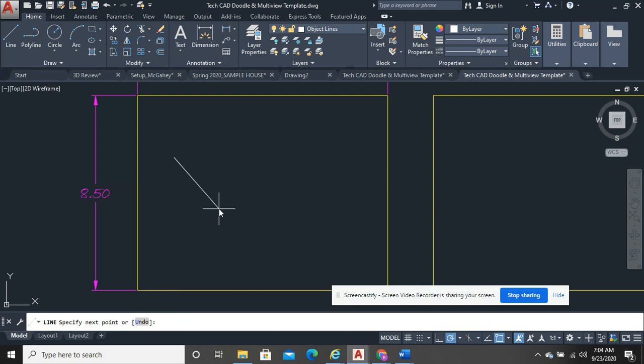So if I do this, I can just type in, like, I want a line that's 5 inches long. All right, perfect. There's one other tool that does that, and if you're doing a lot of stuff that is right and left-ish, look down here at the bottom where this toolbar is. It says Model, and then you have a few other tabs. You see this one that looks like a clock or some kind of gauge. To the left of it, you see one that looks like a right angle.